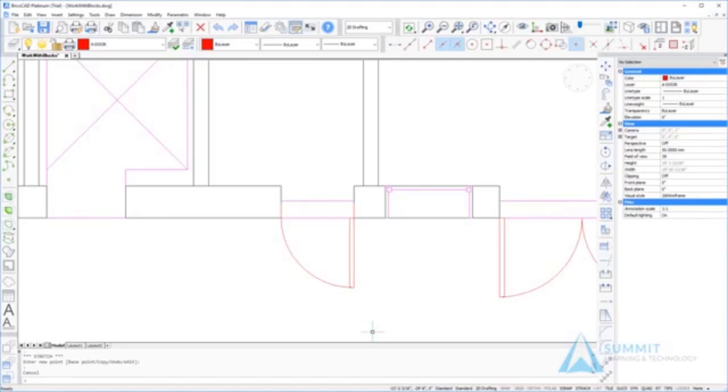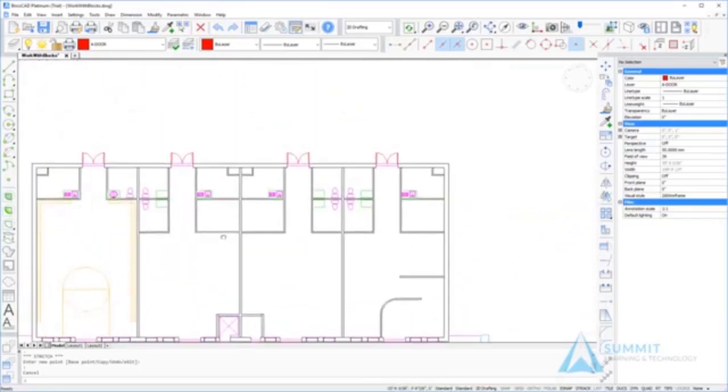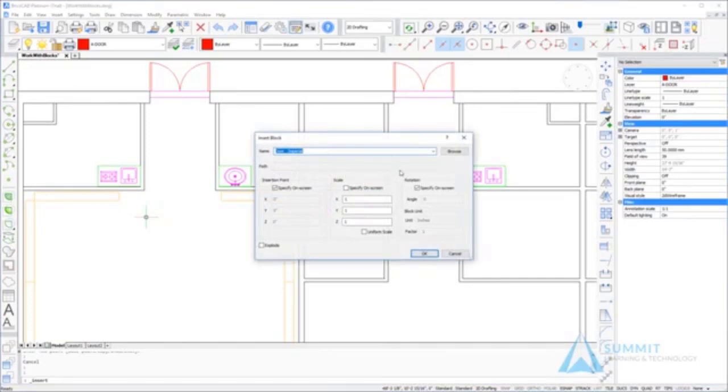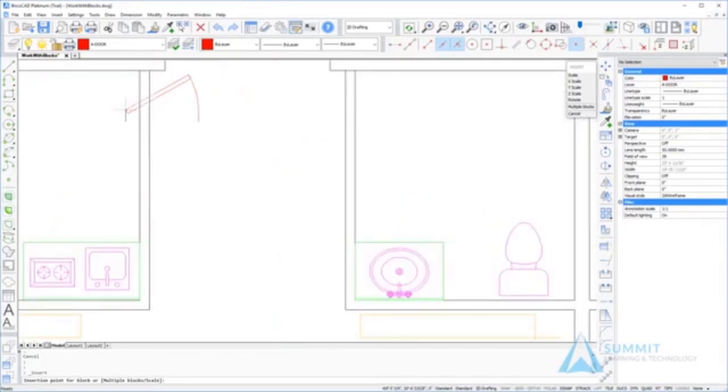Okay, panning up to the next area of the drawing, we're going to continue working with dynamic blocks. Just going to do a different example. So again, starting the insert command, the last block is already chosen. So we'll select the insertion point using our entity object snaps, and we'll place the door in this general location on the wall, and then rotate it accordingly.